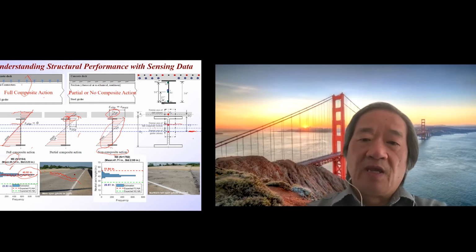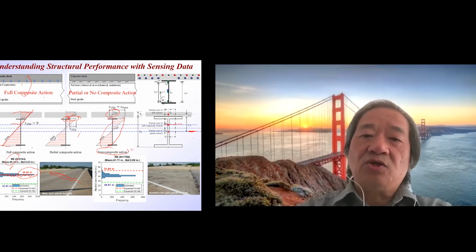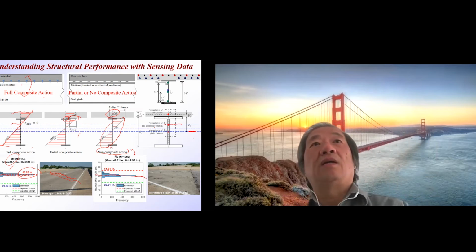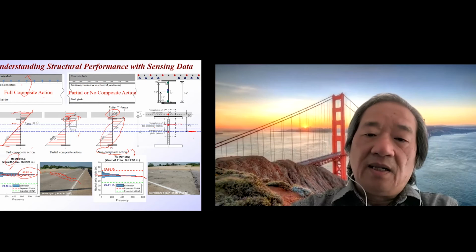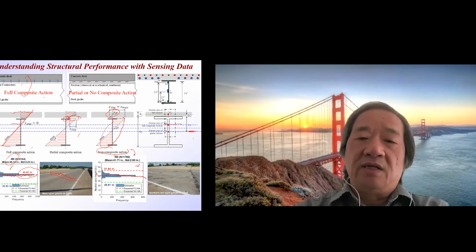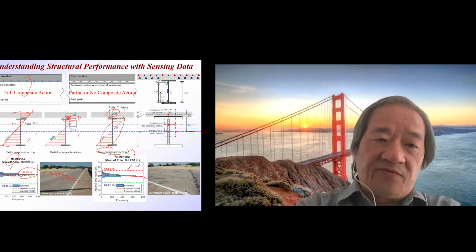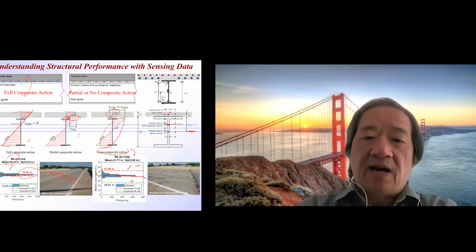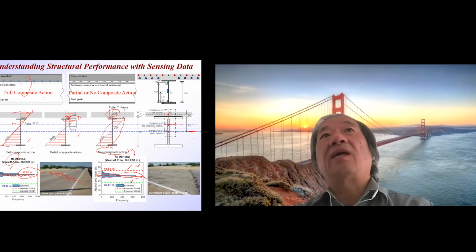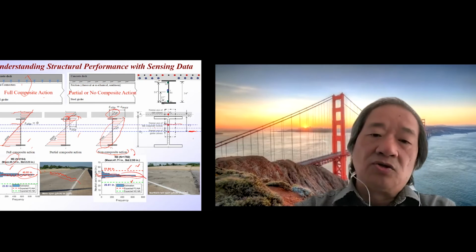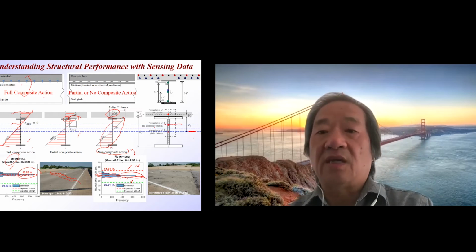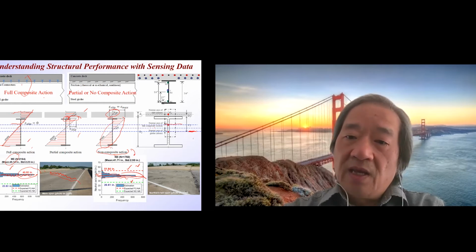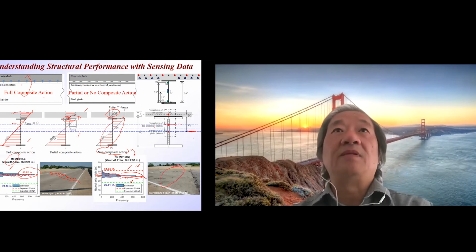Make sure the pavement doesn't crack. But on the other hand, when you're looking at the tail span, okay, you can see the neutral axis of the data doesn't really lie with the fully composite action, it lies between fully composite action and no action. That means there's some partial action, but it turns out that the designer kind of ignored any composite action in that part. What you see at the end is a lot of strain going on, and then the pavement actually cracks.